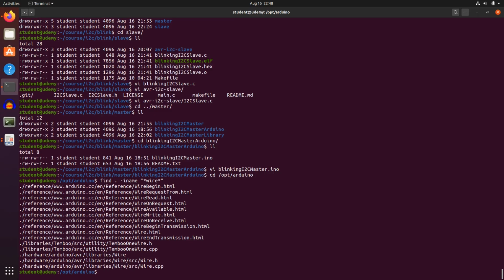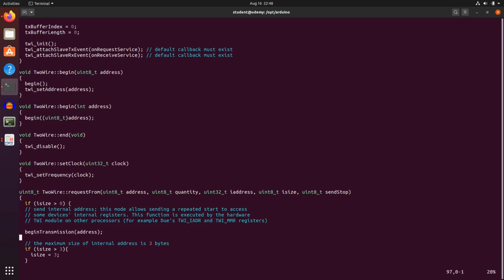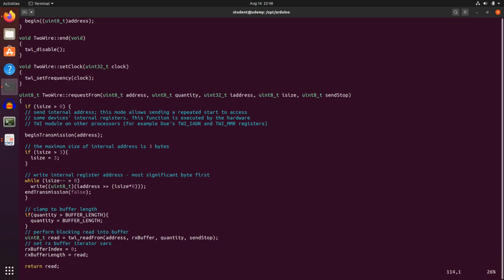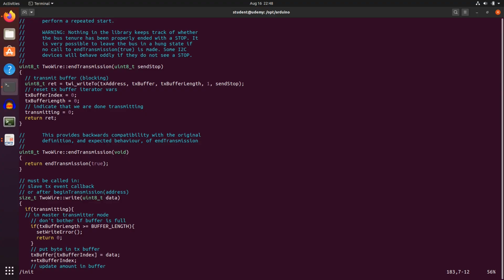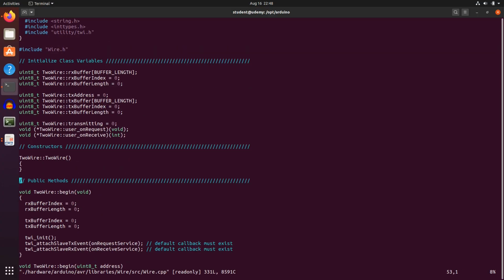And we have here a library. In the libraries, there should be somewhere an init. Search for it. It starts with the wire.begin. There's then this function call, and there is nothing much, but there is a TWI init. Let's see what that is.